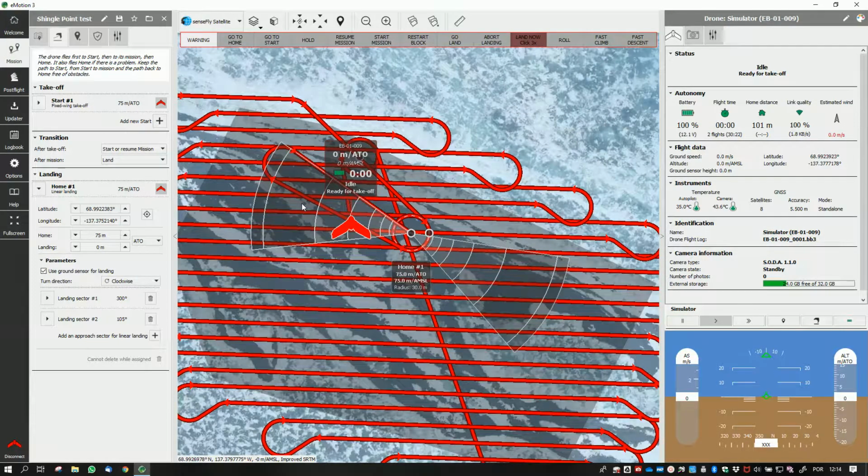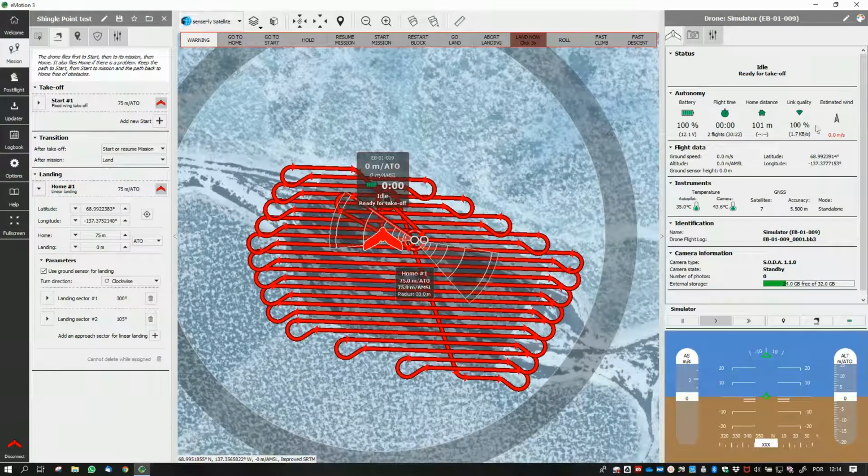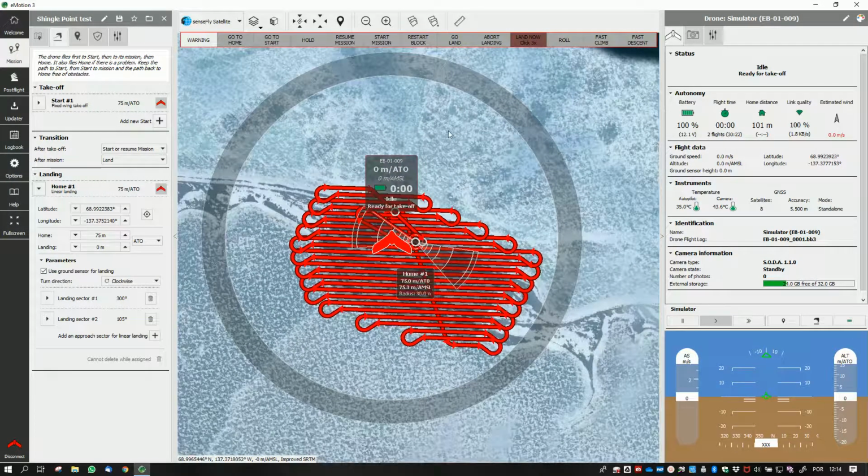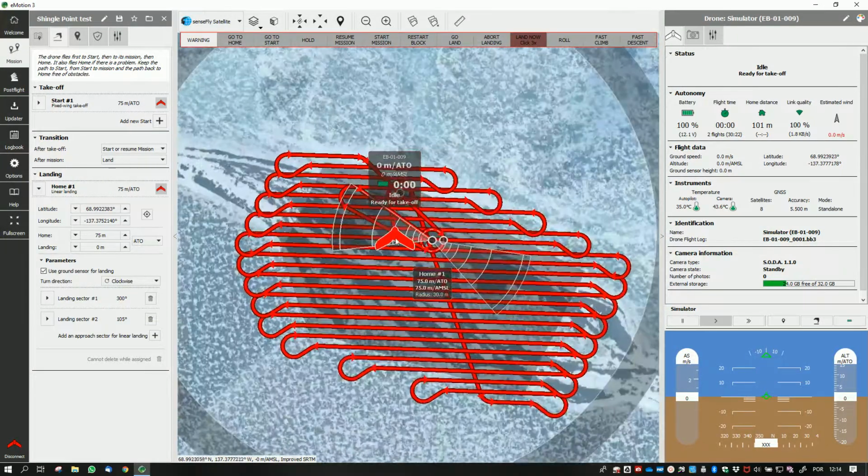If you for any reason lose the link connection, normally what you will see is a link connection lost warning, and the drone position is just freezing. The drone has frozen in the last known position. What I would think you should do is try to see if you still see the drone.